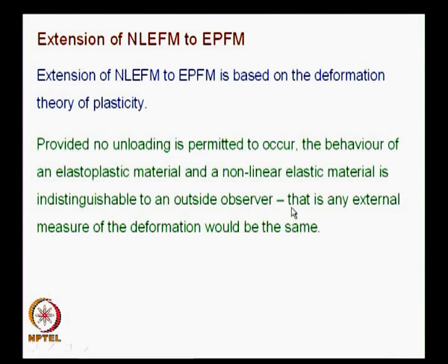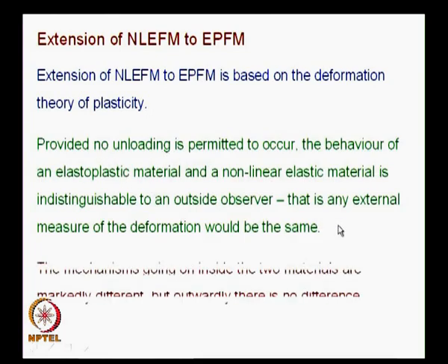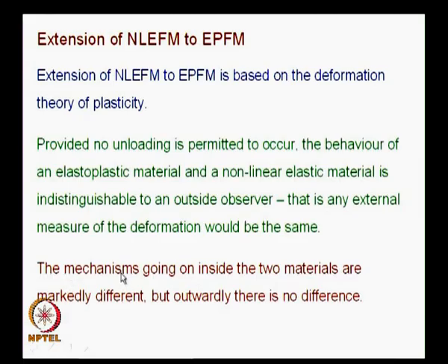For an external observer, it will remain identical. What it means is, any external measure of the deformation would be the same in nonlinear elastic material as well as elastoplastic material. But you have to keep in mind the mechanisms going on inside the two materials are markedly different, but outwardly there is no difference.